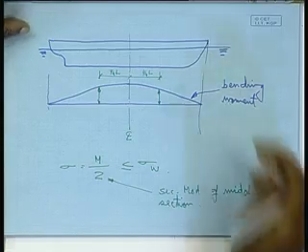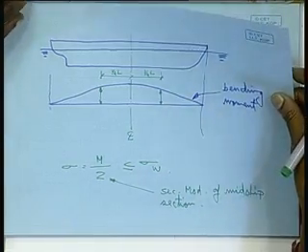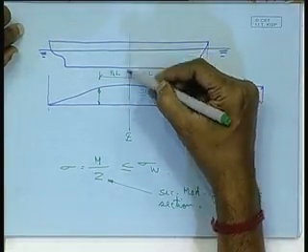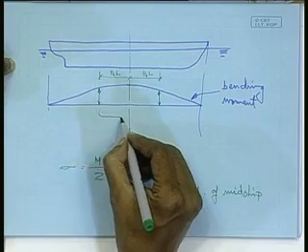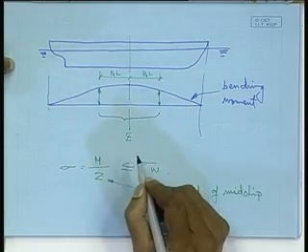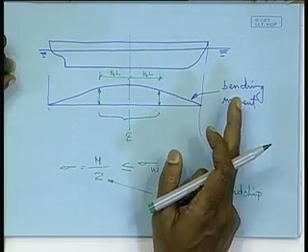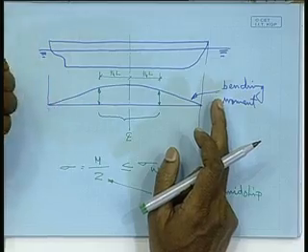right. So what in practice is done is that we do the physical drawing of the midship section, showing all the longitudinal structure members as well as primary transverse members, and that arrangement is continued over this entire length. We have seen some structural arrangement in the forward end construction, and similarly in the aft end, for somewhat similar reasons we have some additional stiffening arrangement.